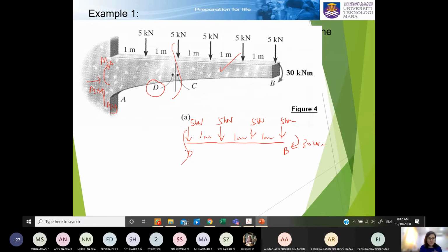May I know the shear force? The positive sign is which direction for shear force? Upward. Yes, upward. And how about the moment? Clockwise. Thank you very much. So this is how you draw these internal forces, and also you have an exerted force coming out from the joint.